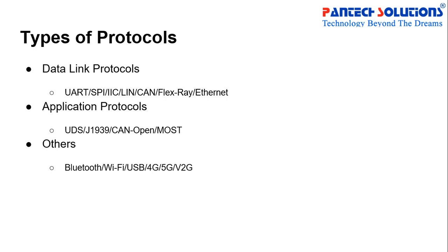For example, if you take a UART protocol, you can transfer all kinds of data. Comparatively, if you take a CAN protocol, you can send integer data, that is called low bitrate data. And if you want a high-end protocol for a high-end file message, you should have an Ethernet protocol.